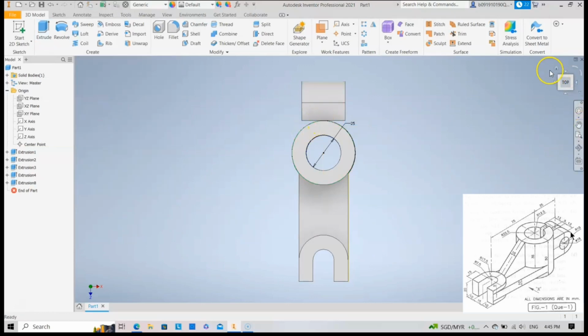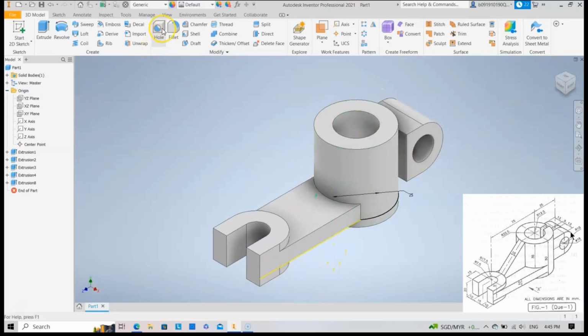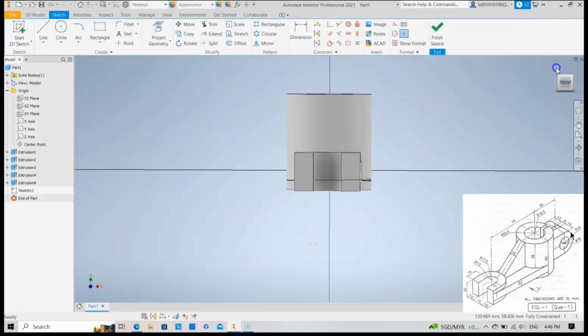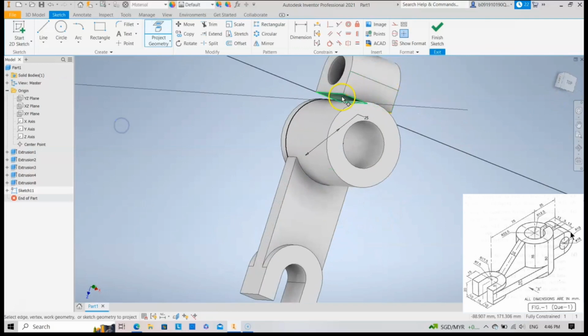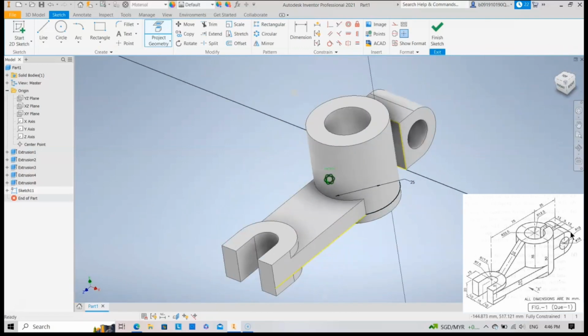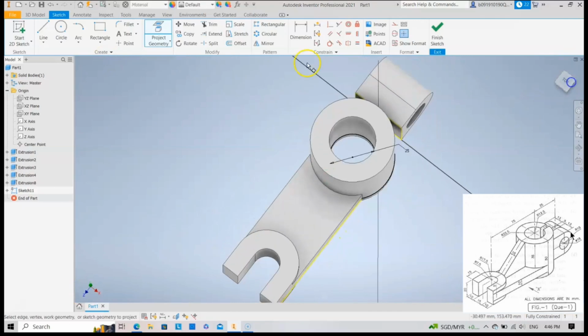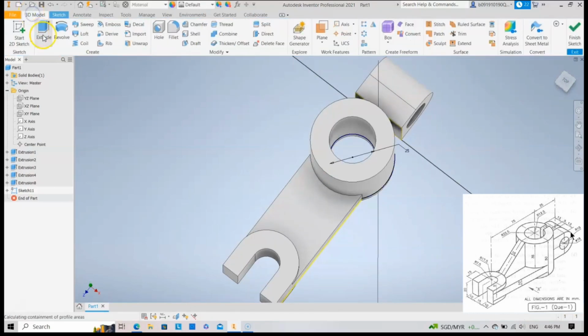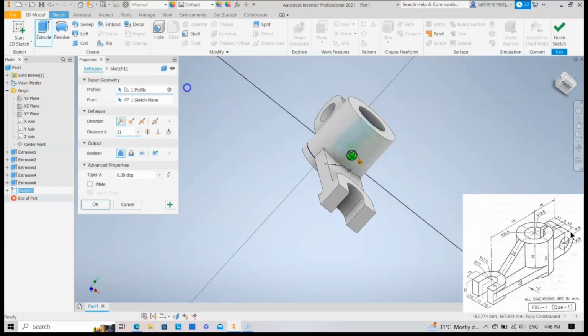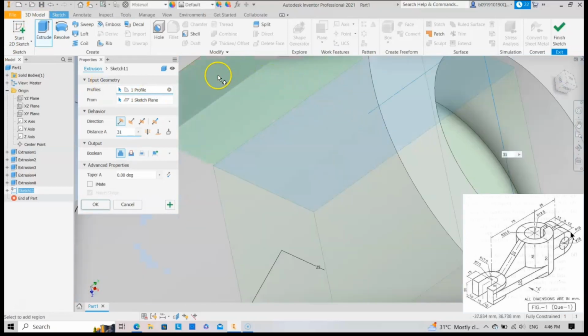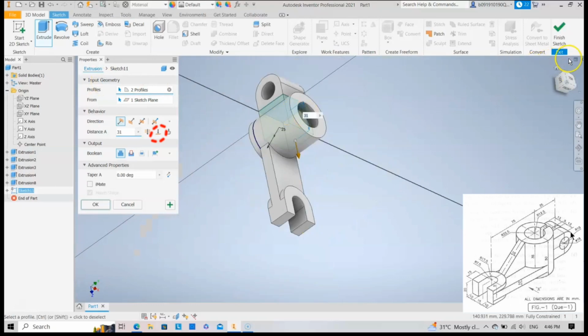To make the part stick to the circle, click Sketch on the flat part near the circle, then click Project Geometry to copy. Then extrude the part using the distance of 2 and click the circle part.